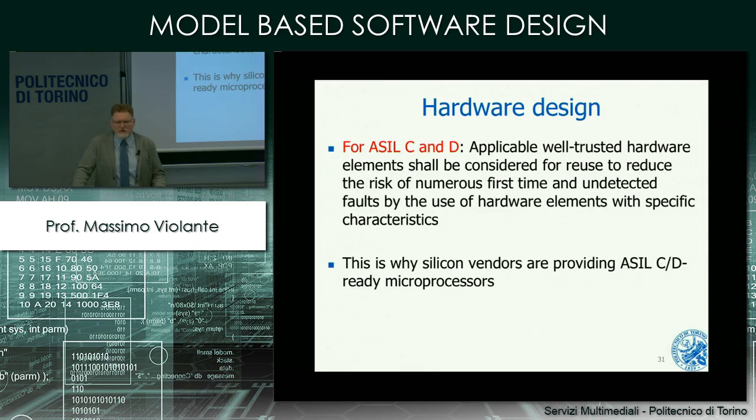And this can be very complex. One technique that is used, for example, is to duplicate the computing cores. So you have one software that is running concurrently on two independent cores. They do the same operation, and then the hardware contains some specific hardware modules that are called redundancy checker, that compare the output produced by the two cores, and if they are different, the output is not delivered to the user. Instead, an error indication is delivered to the user. So the microprocessor is able to understand autonomously whether something is going wrong.